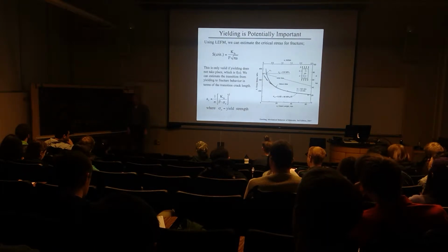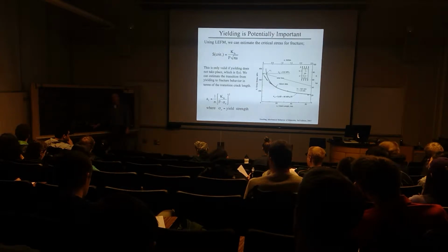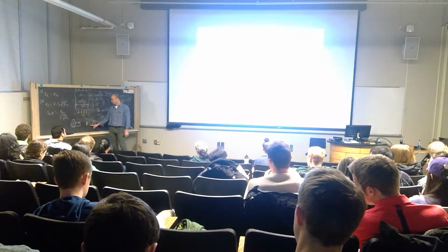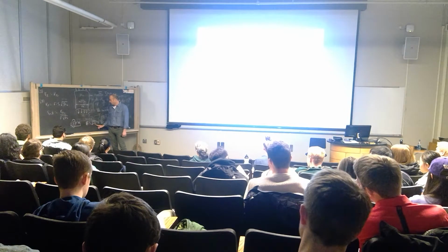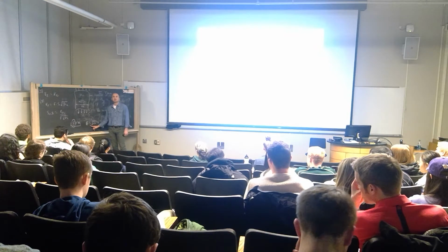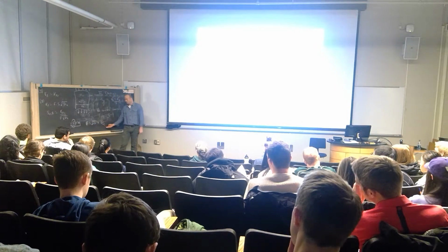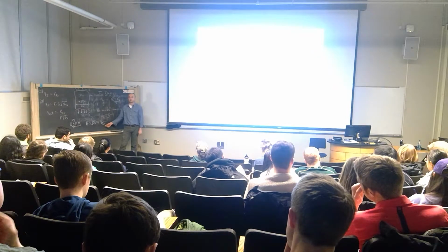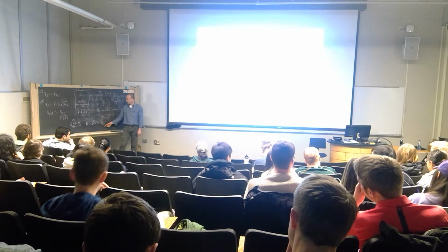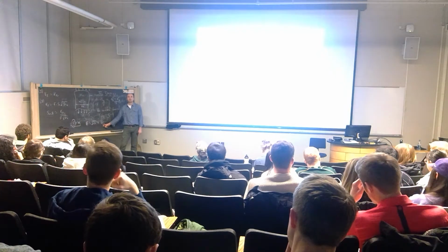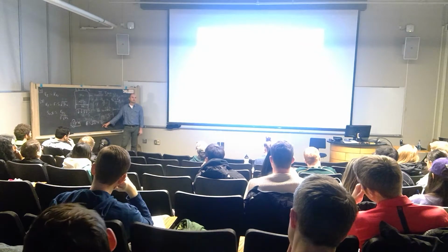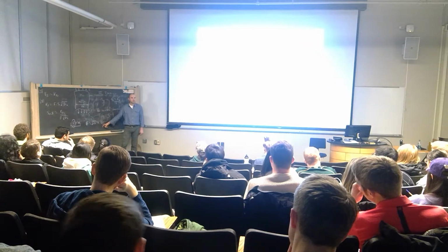Now, what happens if I have that crack length, and I also expect to know what the stresses were on that structure at the point at which failure took place? So I have the geometry factor because I know the flaw length, and I know the stress. What can I calculate? I can calculate what apparent fracture toughness that structure is in, right? And what happens if I find out that it's different than what's reported for that material? I made a mistake. Shoot.